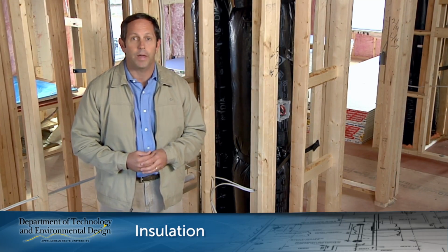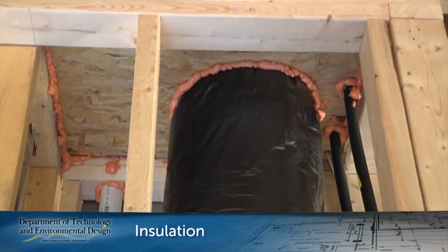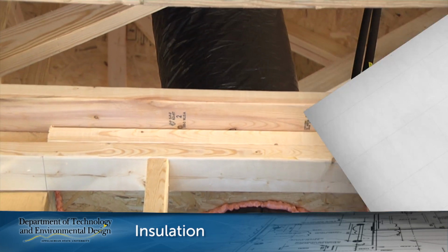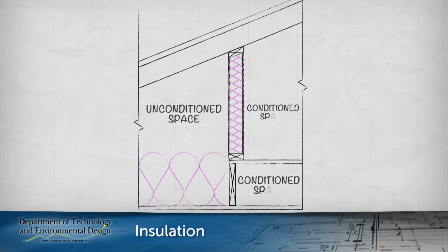Basically, all walls, floors, and ceilings must be air sealed. That includes chases and drop ceilings, which must be capped. To separate conditioned space from unconditioned space, blocks must be placed directly under knee walls. Now let's go to a finished house and see the requirements for access hatches and doors.